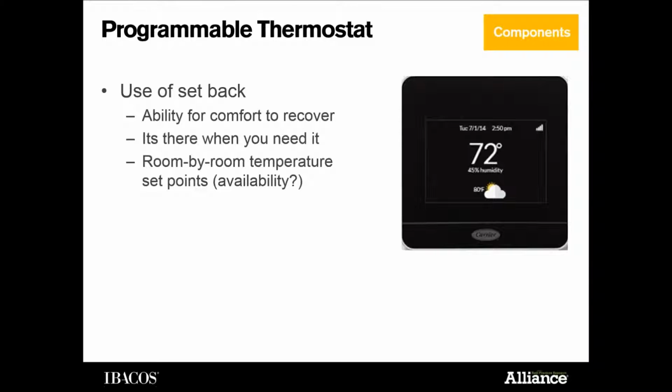Well, if you set back your thermostat in a low-load home on a really cold day, say 5 degrees, that home will actually take a while to cool off. But then when you want that home to get up to temperature, it's going to take almost the same amount of time. So it's going to have a long drift to get to the temperature. So why do it? Why not just keep it at a certain thermostat set point and not have to worry about it?